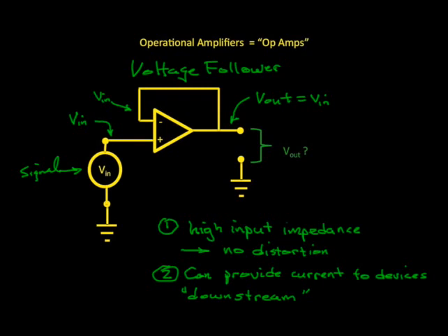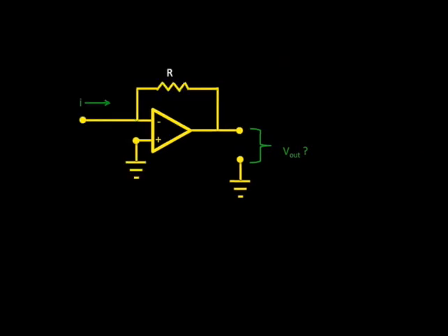It's often used in different instruments that are used to measure a voltage signal from some transducer or detector, and this is very useful for buffering, essentially, the signal source from devices downstream from this point where we might be manipulating the signal. We often have a device that produces a current signal. Voltages are easier to manipulate than currents, so we are interested maybe in converting this to a voltage signal. Here's a common method for converting current to voltage.